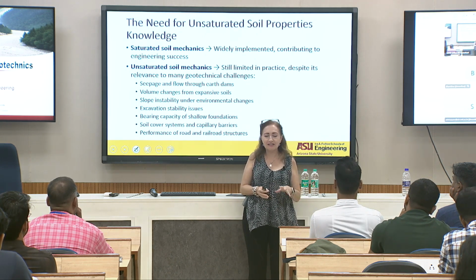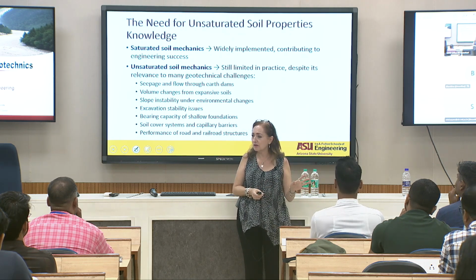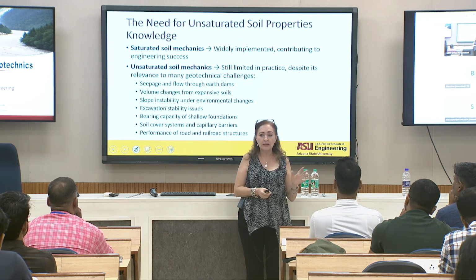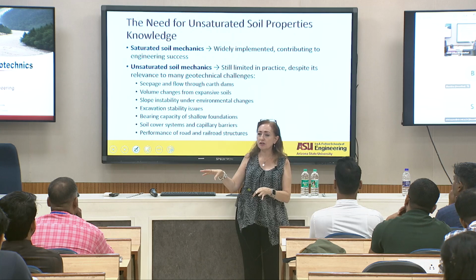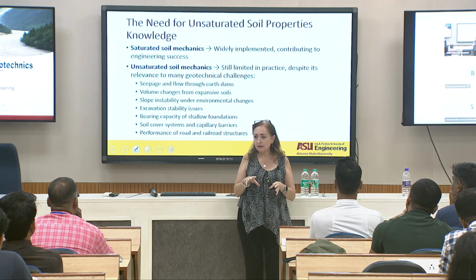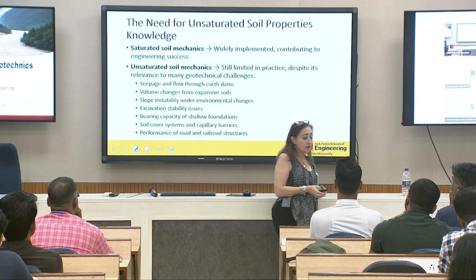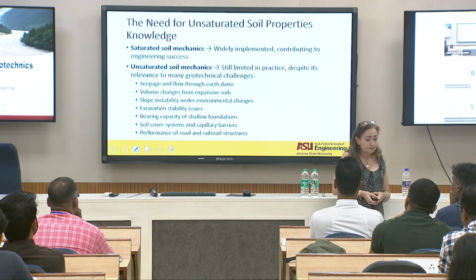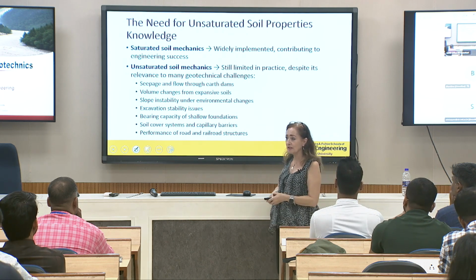Just talk to me about, and fine, we talk to them about volumetric water content or gravimetric water content, but in our classrooms and our laboratories, we should be doing fundamental modeling based on suction, which is our fundamental stress state variable, right? Why? Because there are many geotechnical challenges that are a function of unsaturated soil.